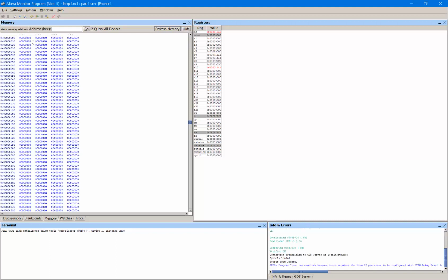So once we do that store byte, we should expect that in this 0 address here, it would show 1 1 in the first 2 digits. Now, because all of these addresses here, all the way up to 1FFF, are mapped to slave register 0, we should see that there will be a recurring pattern.